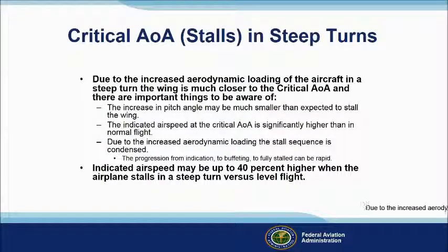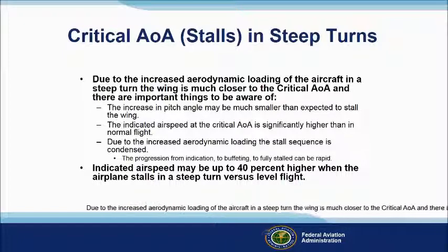Due to the increased aerodynamic loading of the aircraft in the steep turn, the wing is much closer to the critical AOA, and there are important things to be aware of. The increase in pitch angle may be much smaller than expected to stall the wing. The indicated airspeed at the critical AOA is significantly higher than in normal flight.